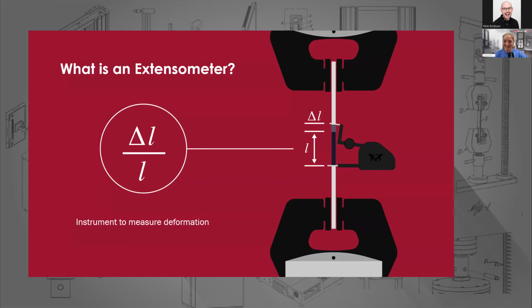Okay, perfect. So back to when you're setting up your extensometer, you're going to choose an initial gauge length and get that set. So as your specimen begins to deform, that delta L that we call out on the slide, that's the change in length. And this can either be measured physically or virtually. For physical measurement, that deformation is translated into an electrical signal. That signal is then output to your test frame or controller, and it will get translated into the stress strain data that you see from your frame in your software, those curves that are generated.